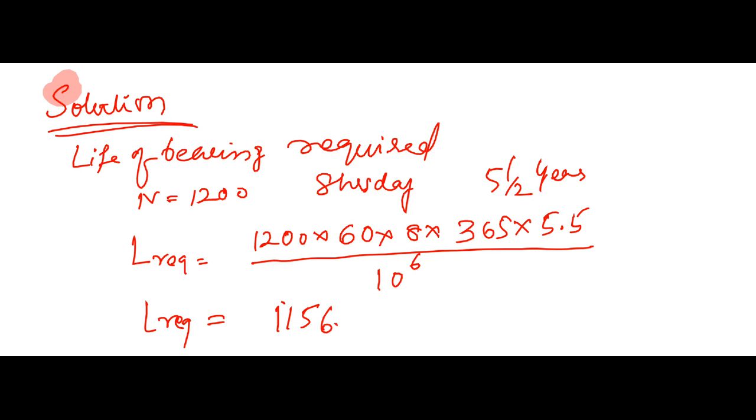It is 1156.32 millions of revolutions. This is the required life of bearing, which has to sustain for 5.5 years and working 8 hours per day.